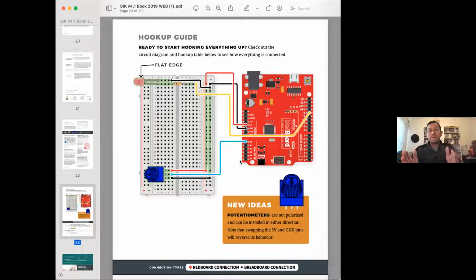It can vary. And so we want to be able to capture that, and that's where we'll need an analog in. It's not just telling us if it's on or off. We want to know the amount of voltage that we're getting. That's why this potentiometer is connected here with the blue wire to this one at the analog in section. And so now let's go to our